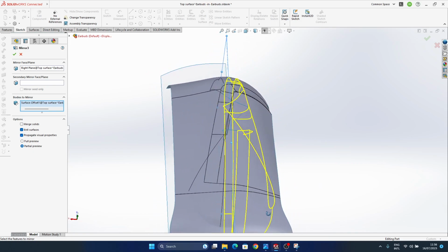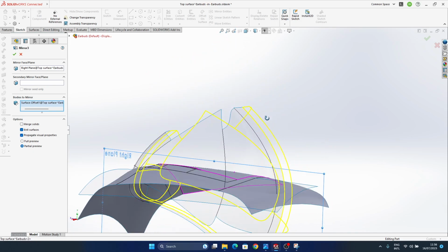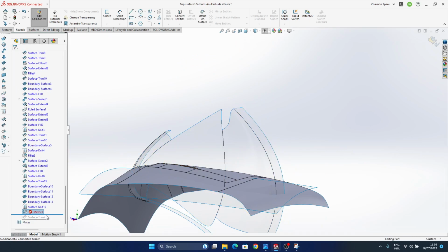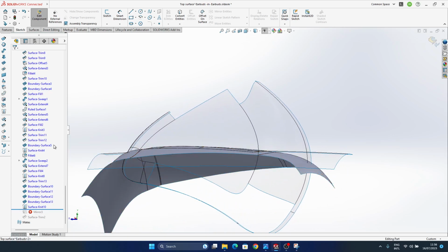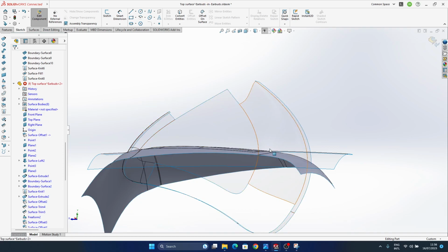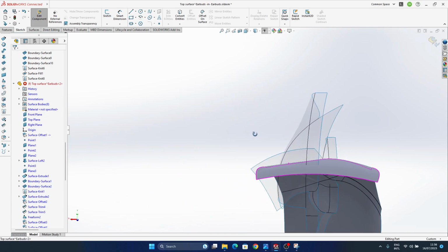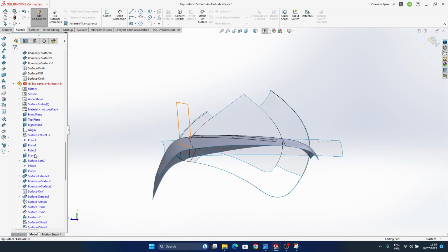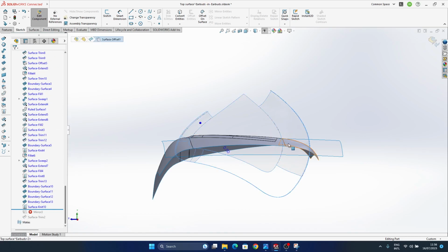Yeah, so I'm doing this. Yes, intersecting surfaces. That's why he has a mirror problem in there. So I'm going to use the top surface or anything above. Yes, let's make a sketch and cut those input surfaces first, so that we don't have that problem anymore right at the end.